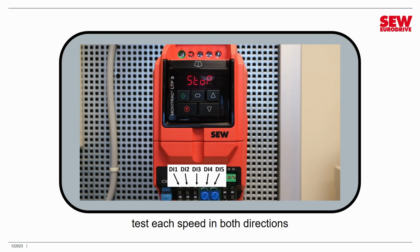And just to review what each of these switches does, digital input 1 is the enable-disable, the run-stop switch. Digital input 2 is forward or reverse. Digital input 3 and 4 form a binary number of 2 bits. The least significant bit is on the left, so that's the switch. The potentiometer is the bit on the right, the most significant bit. And then finally, digital input 5, which is the second potentiometer, selects between the fast and the slow ramps. When it's off, we get the normal slow ramp. When it's on, we get the fast ramp.